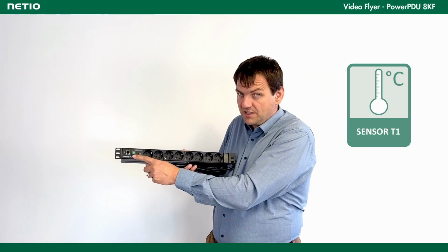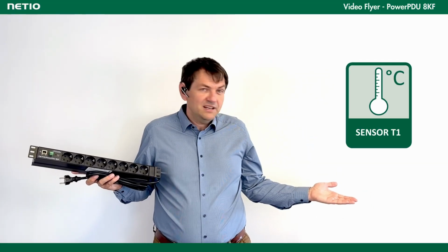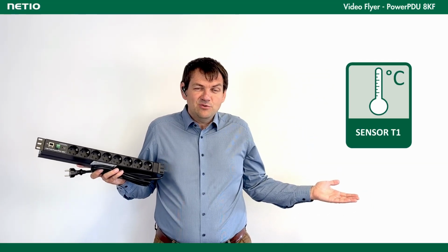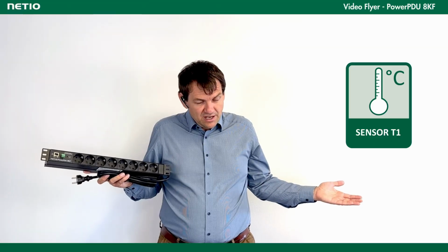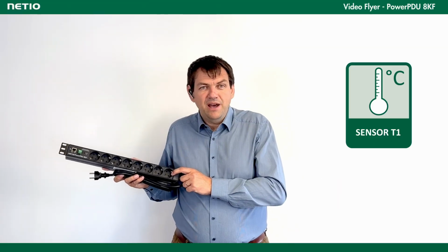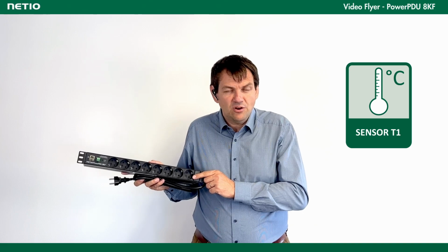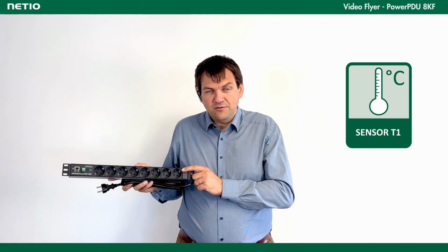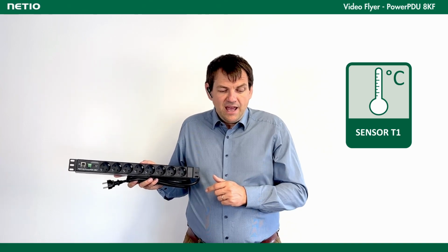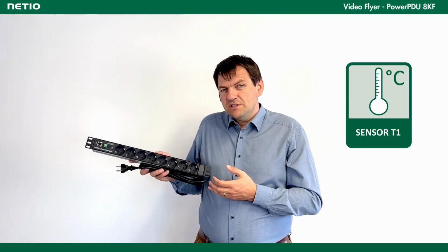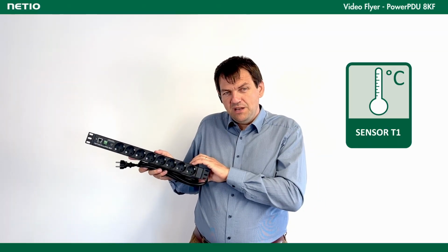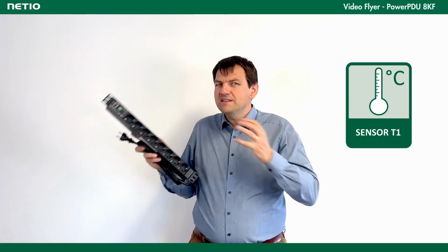On this green terminal block, you can also connect a temperature sensor, and the temperature sensor can be used for a thermostat. So basically you can say that output number 8 will be switched on if the temperature is above 25 Celsius or below 25 Celsius, depending on whether you are cooling or heating, and things like that. So all these features are again inside the PDU only, so you don't need any big system for that.